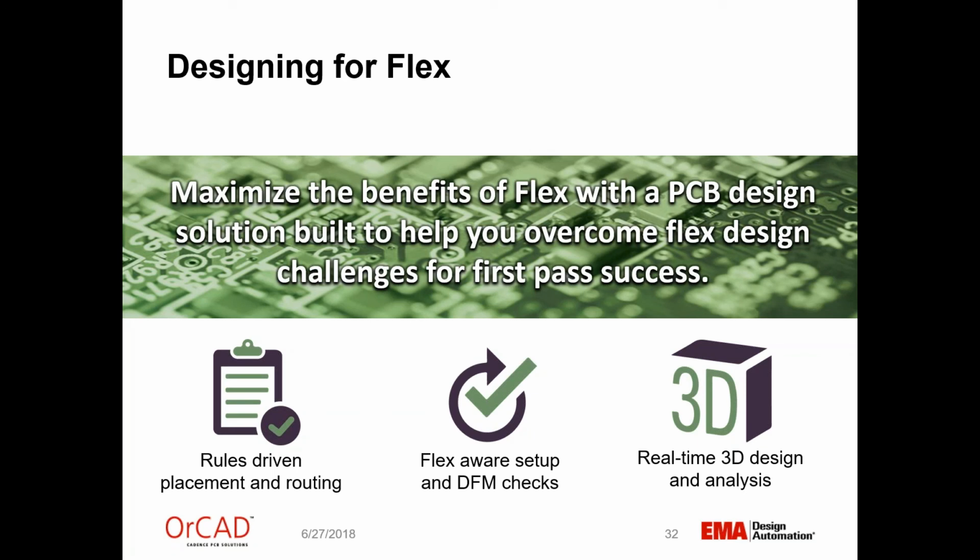Okay. Is cross-hatching only necessary in areas where there are bends or folds? You know, it's preferable to use crosshatch in those areas. Usually in rigid boards, we prefer solid. Okay. What version of PCB Editor are these flex capabilities available in? 17.2. Okay, that one's easy.